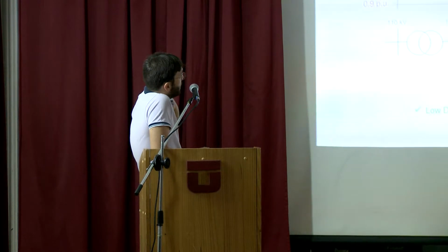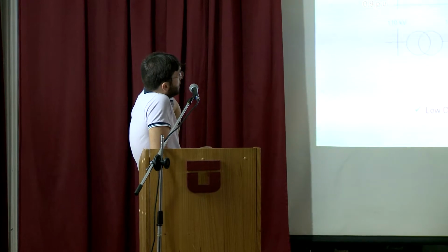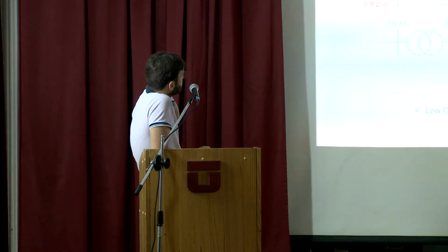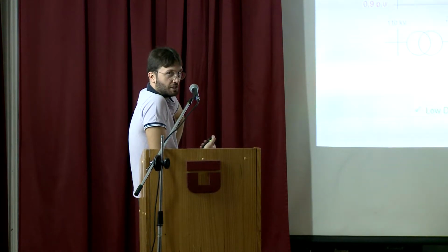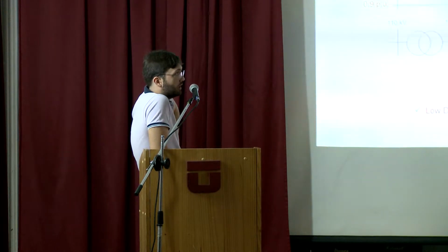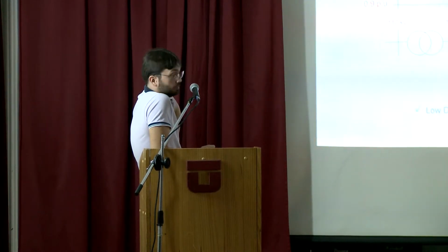Then I am here at the medium voltage to low voltage, and at the medium voltage to low voltage I have some distributed generation. Actually this point should have been here. They got a bit misaligned, but let's say as long as the power goes here, you can imagine the voltage goes down, but if I have distributed generation, actually the current goes in the other direction, so the voltage from this point will go up.